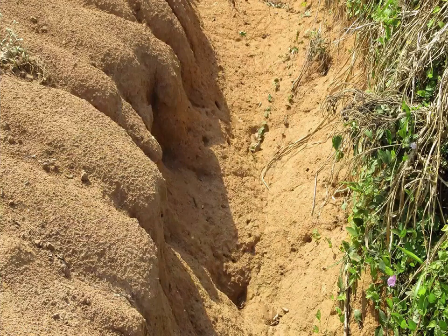So as a result of these processes, siltation and sedimentation raise the water level, which results in channel widening. Here you can see there is a widening or a gap between these layers of the soil, and it can also be referred to as gully erosion.